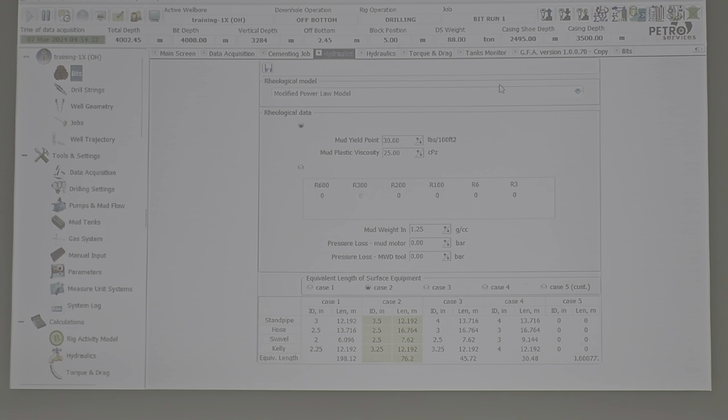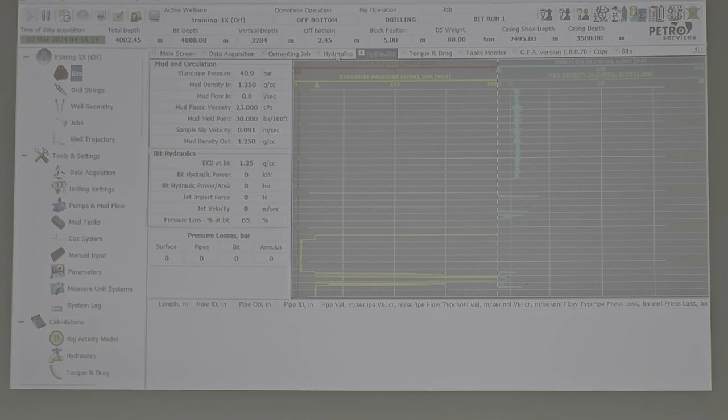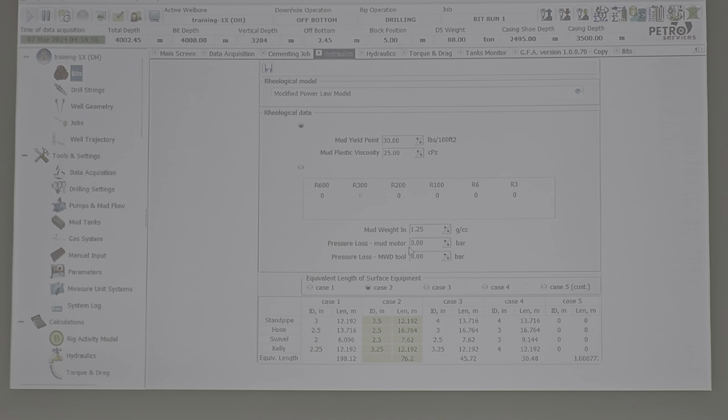So you have to ask the directional company: what is the pressure drop in your tool? It means how much pressure should be added theoretically when I am using your tool. He will tell you, okay, 200 bar for MWD and motor. No need to ask him what for motor only and what for MWD.